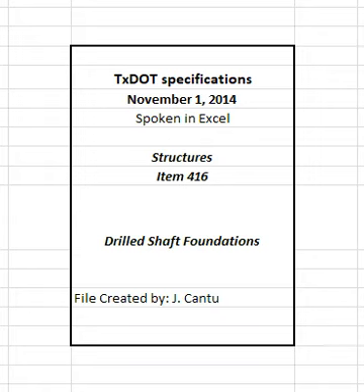Use an airlift or proper size cleanout bucket, just before placing reinforcing steel, to remove any material that may have fallen from the sides of the excavation or accumulated on the bottom after the completion of drilling.